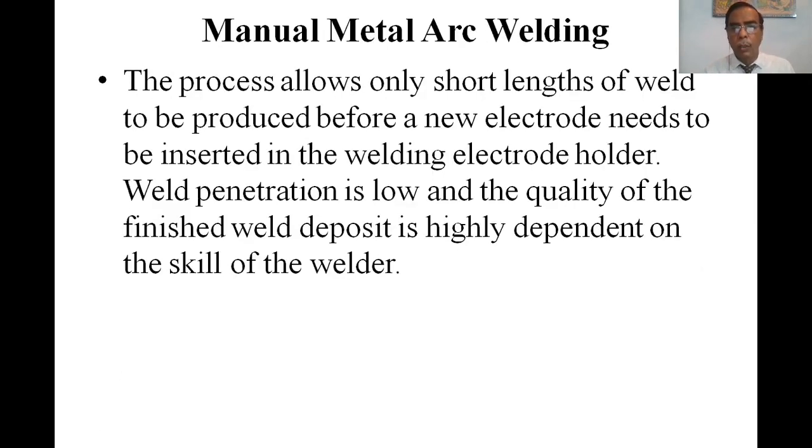The process allows only a short length of weld to be produced before a new electrode needs to be inserted in the welding electrode holder. Weld penetration is low and the quality of the finished weld deposit is highly dependent on the skill of the welder.